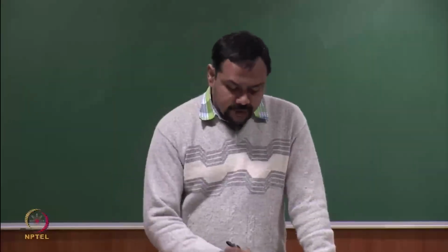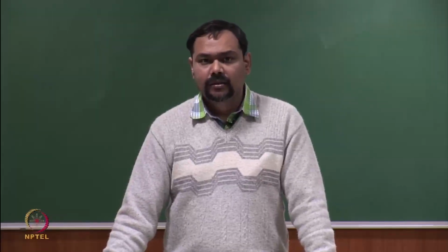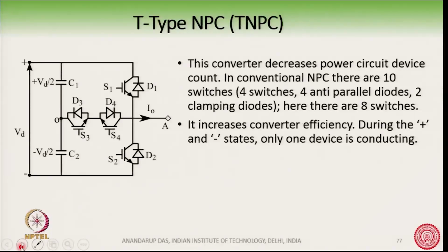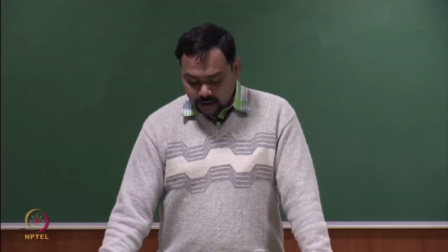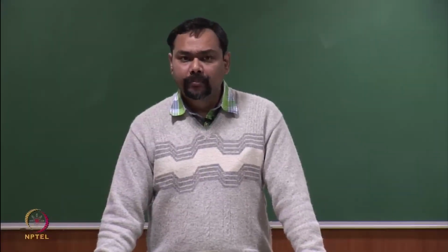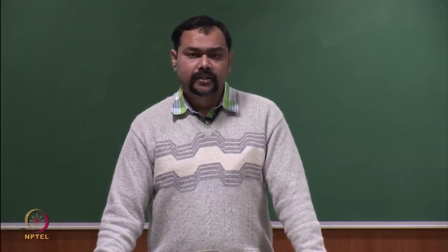But in this TNPC topology, there are 8 switches. Okay. Of course, these 8 switches have different voltage ratings, but overall it has been reported that this operation increases the converter efficiency.